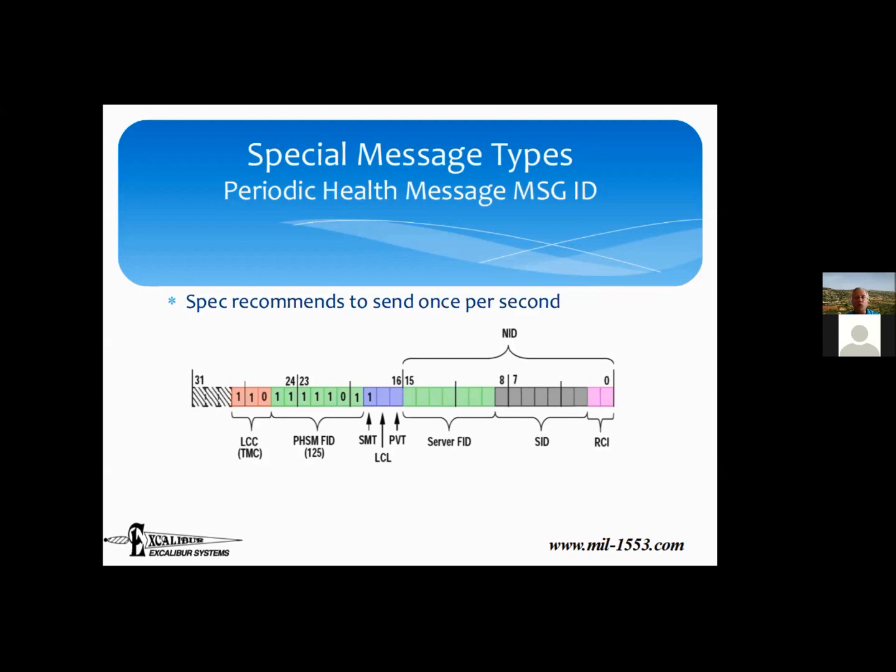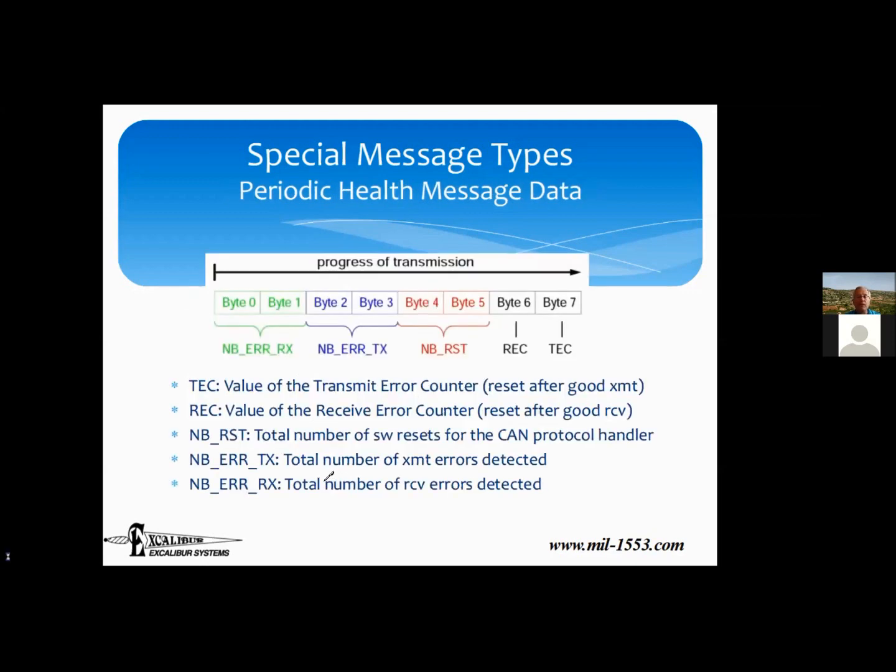And I'm not taking you off because you're an inertial navigation system. I'm taking you off because this particular box is not working. So the needs are different in a health message than they are in a standard data message, and therefore the identifier is different as well. So here, the kind of information I'm going to need is really who you are, which physical box you are. Now, that was the identifier we talked about.